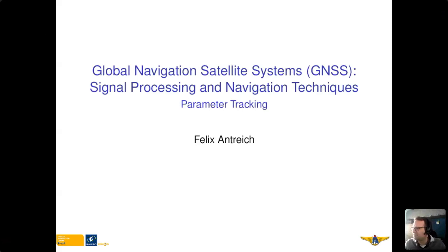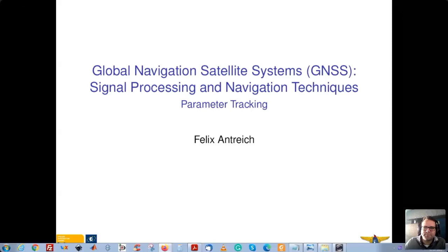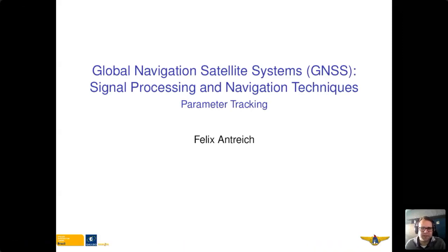So let's talk about parameter tracking. We have seen this morning how we can initialize the parameter estimation, how we can detect which satellite is present. This is done by signal acquisition, and we have seen the parallel delay acquisition using the circular cross correlation, calculated with a DFT, a discrete Fourier transform.